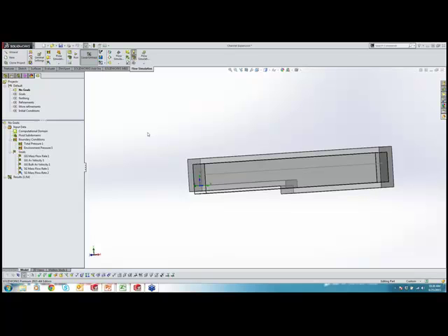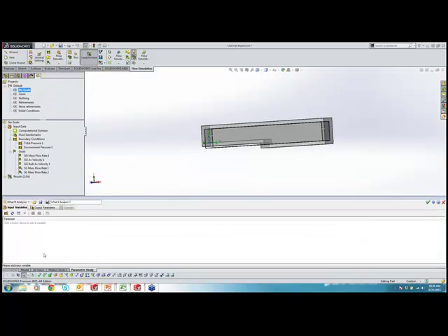However, one thing you can do if you haven't used it before, let's say you have a valve with a piston. I don't have a model here on hand, but if you right-click on your goals or on your study and come in here to parametric studies, you can do a study where you have a set of positions for the valve, right?